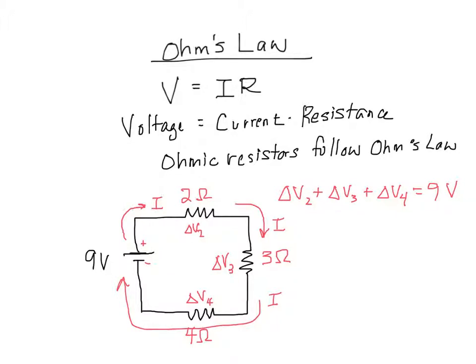What we're going to do is we're going to use this Ohm's law. The reason Ohm's law is useful is that if you know the amount of voltage you have in a circuit and you know the amount of resistance in that circuit, you can figure out how much current is passing through the circuit. Knowing the amount of current going through a circuit is very important. It's important in your house because wire is sized based on the amount of current passing through it. You don't want to have a real small wire with a lot of current going through it because it'll heat up, it could cause a fire. That's like trying to push a lot of water through a tiny pipe. You know, you're going to have problems, the pipe might burst.